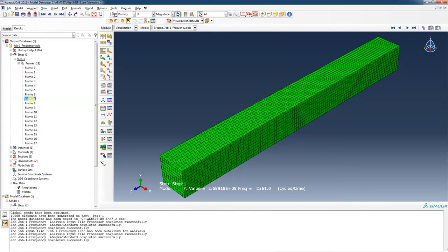Now one thing that you'll notice if you change the lengths, this is now a 200 millimeter long beam, is that you'll start to be less beam-like when you get shorter and shorter lengths. Right, so what I'd like for you to do will be to try a series of different lengths, maybe shorter or longer lengths than 400 millimeters, and see how that influences the first maybe 3 natural frequencies that are calculated, and try to put together a report on that.